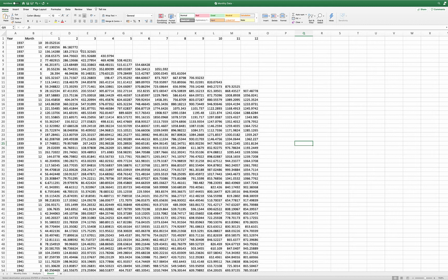So what you now have is a set of time series of the rolling n month total plotted against the final month of that n months. And this is the data that you should use to estimate your return periods at those different scales of aggregation. Now what you will notice is that you progressively lose a month in here, so you might have to discard some of this data up here to make your analyses consistent.